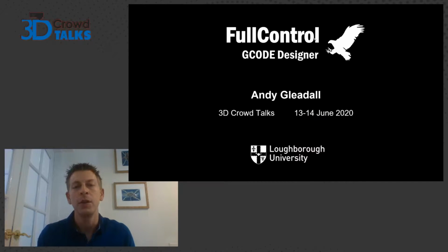It's new research for controlling 3D printers in a more precise way than what would normally be done using the traditional software. So in this talk, I'm going to mostly go through a fair few examples of what sort of structures we've produced with this idea of basically telling the printer to move around in exactly the way we want, taking out the normal slicing approach. So we don't have a CAD 3D model that's sliced. We just define the toolpath of the printer directly.